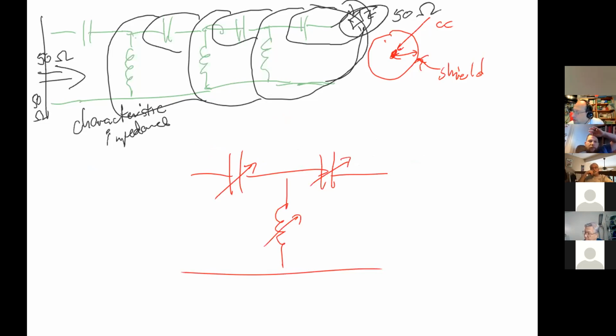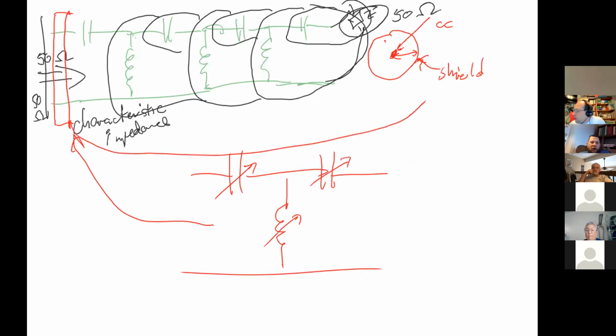It would go right in here and allow you to tune the capacitors and inductors so that the impedance, whatever it was, from here to the outside world would be matched to what your radio was looking for, and allow you to believe that you're looking into a 50 ohm impedance in the real world, and that the power coming down from the antenna through the feed line is matched properly to your radio.